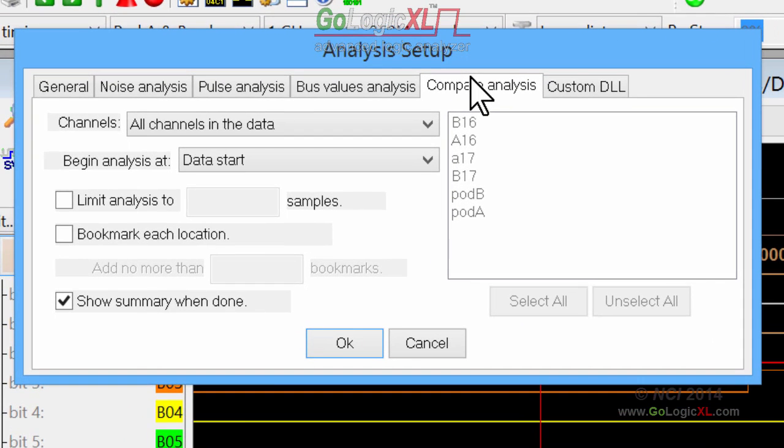The comparison analysis is performed in the time domain so that conflicting sampling rates or sampling methods can be compared correctly. For example, trace data captured with 1 gigahertz transitional timing can be compared accurately with reference data captured using 50 megahertz normal timing. Now there's no source trace option in this because you must have trace and reference data open at the same time in order to compare it. So all the options here have already been covered.